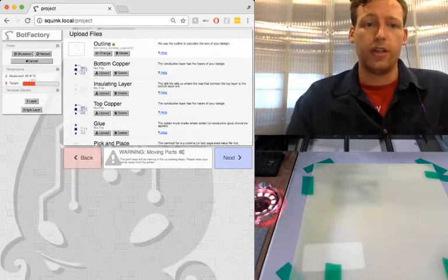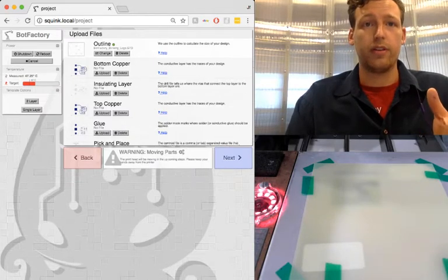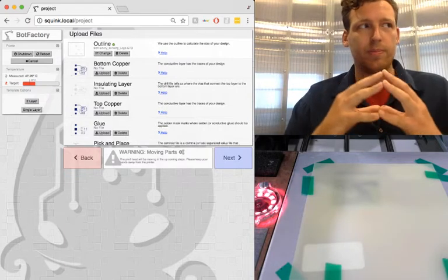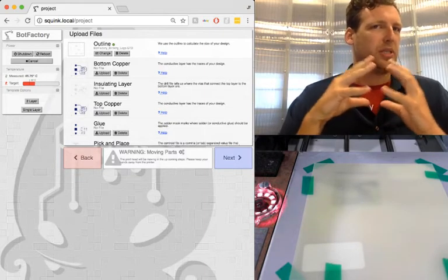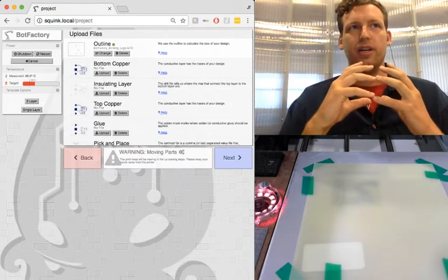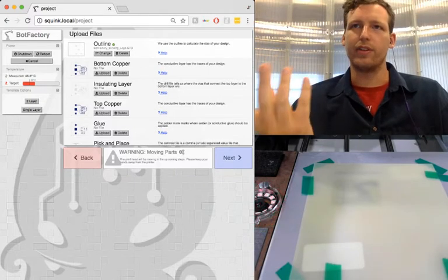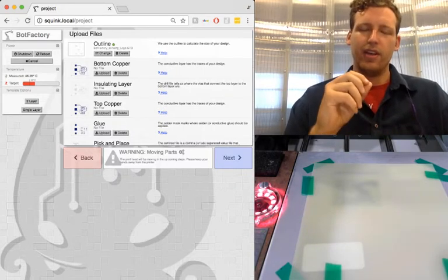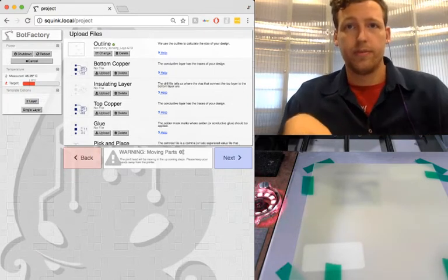And then the top, basically when you're uploading the insulating layer, it's going to be a drill file, a file that essentially defines where you would be drilling. So there's a bit of a misconception about how exactly we print multi-layer boards without a drill head. I want you to imagine a machine that essentially prints the inverse of a drilled board. We're printing the insulating layer of UV curable polymer, and we're leaving gaps where the bottom layer and the top layer will be able to connect.